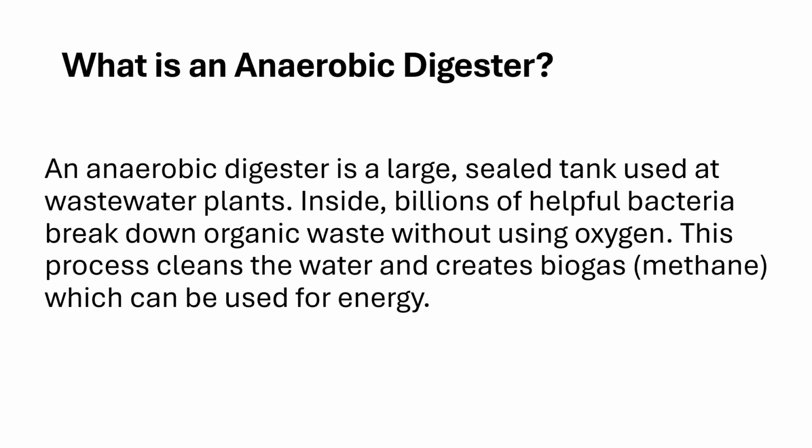As a safety feature, we do have flame arresters. We're going to burn that methane off. Well, if we're going to burn it off, we might as well get something out of it. We might as well get a return. And that's what some plants do. They'll take this methane gas from the anaerobic digester, and they'll use it to power a generator to produce electricity and power the wastewater plant.